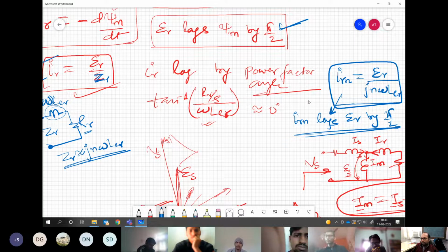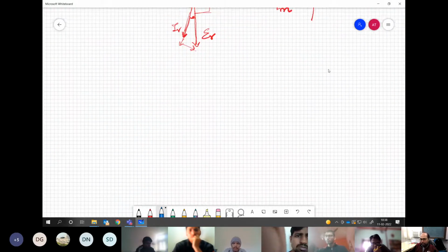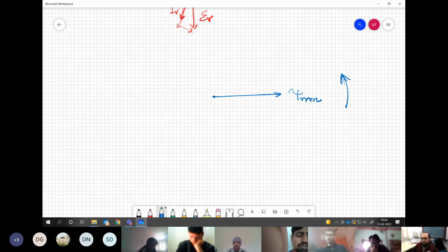For simplicity, you may even ignore the stator resistance and the leakage compared to LM. So the phasor diagram for any harmonic component can be drawn as follows. I will again take the flux first and towards the same direction. Let us say this is also positive sequence, for example, we have taken an nth harmonic voltage which is having positive sequence, not all have.